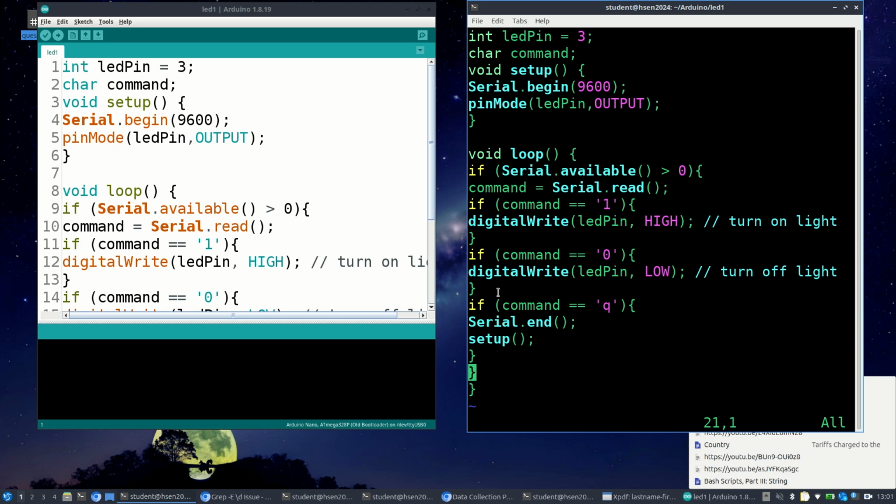The idea is that if you don't put a resistor in, then the current is too big. It's too big for the diode to handle, for the LED to handle. So you have to put the resistor in there to attenuate the current. It burns off some of the energy, right? Basically, that's what it is.